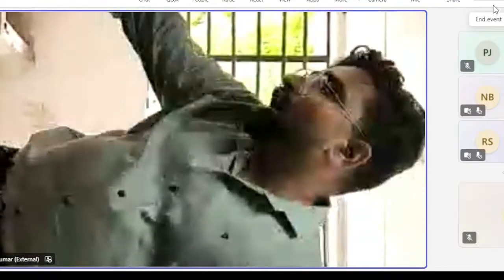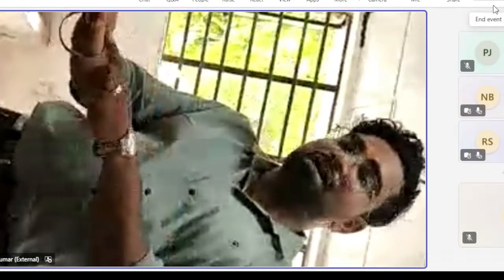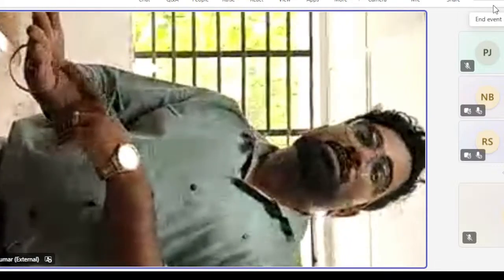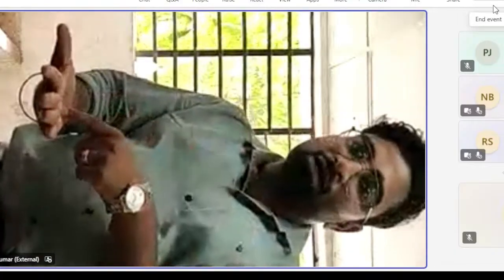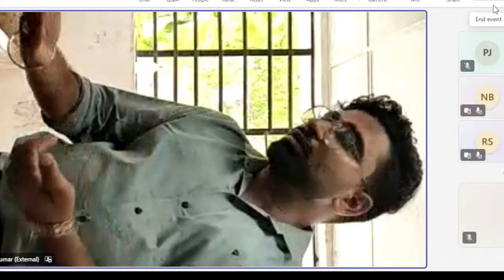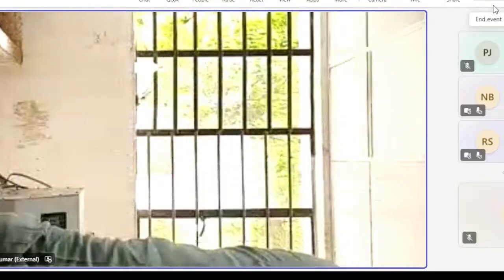So after depositing this, what do we want? I have earlier told you that if we directly close the program, the wire gets welded to the melted part, and we don't want that. So for that we want some spacing. In that direction, Z should go up by 2 and then the program should stop. Right, so everything is okay.